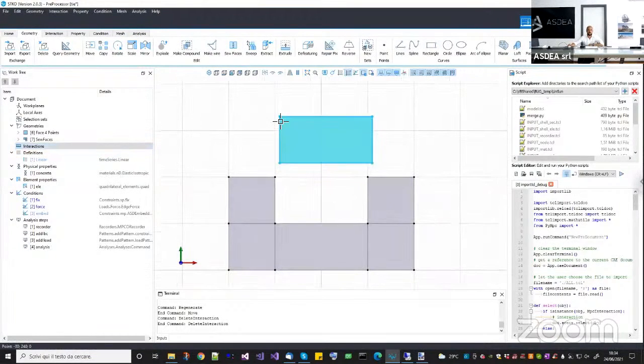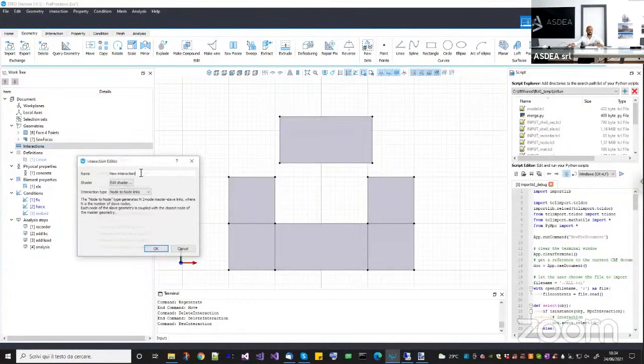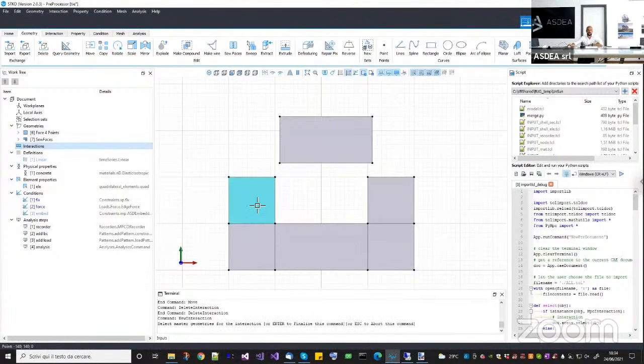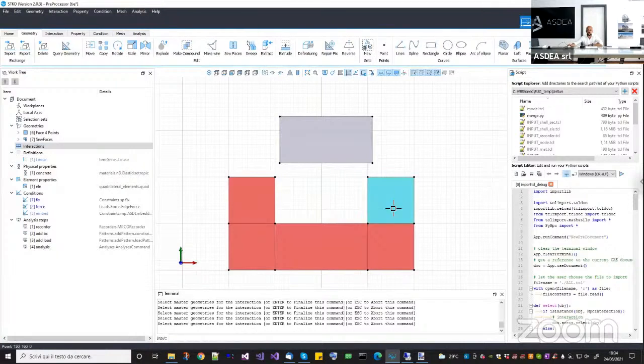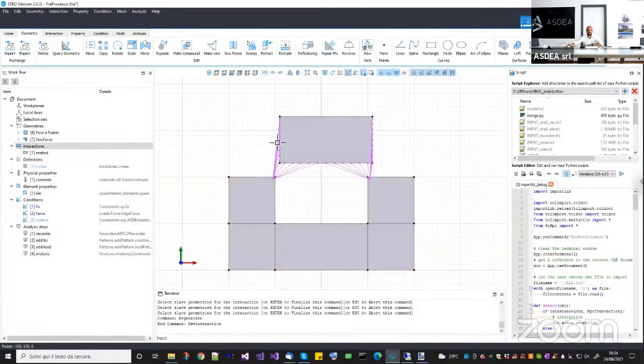So let's say I want to embed these borders to move exactly as these borders here. I do the same as I did before. Interaction. Embed. Just remember always node to element link for the embedding. So what is the master now? The master is the embedding solid, so the surrounding faces, as I did before. Right click, and then the slave. The slave should be these edges because they are the only ones that I want to attach. Right click, and now each one of them will be connected to the nearest point of the face. Once I've done this, I can move it back.